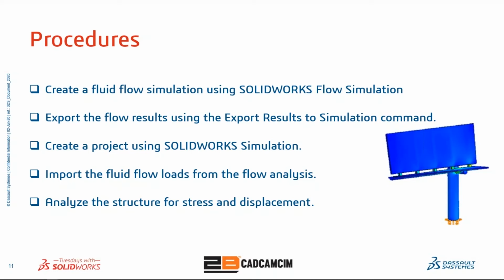First of all, we need to create a flow study, then the next step is to prepare the SolidWorks flow results for compatibility with SolidWorks Simulation. This is accomplished through the Export Results to Simulation feature found in the Flow Simulation tool.